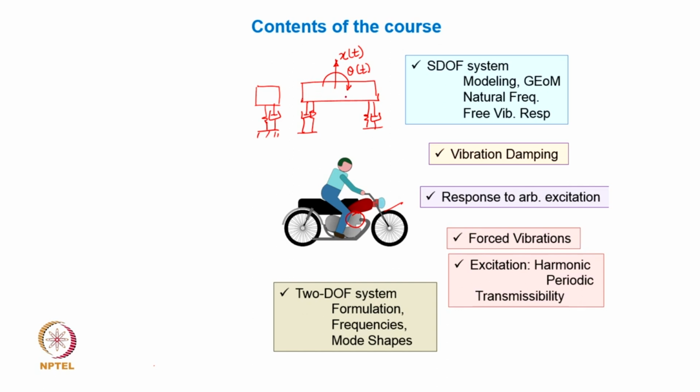a point mass can have 3 degrees of freedom, that is 3 translationals, and if we account for a mass with a size like a chassis, it will also have 3 rotations. So, associated with it are the 3 inertias, and then you can have 6 degrees of freedom in space, which will be the 6 degrees of freedom of this system. But if you want to limit yourself to planar vibration or planar dynamics, then x, theta, maybe y if required later, you can have these 3 degrees of freedom for sure for analyzing this motion.